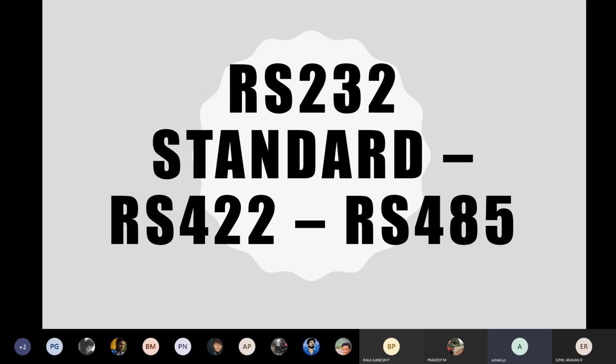As well as, the SCON register is used for sending and receiving the data. So when I want to send and when I want to receive the data, in order to enable the transmission and reception, I will use the SCON, serial control register. So these are the two registers which I will use for communication purpose in the microcontroller.